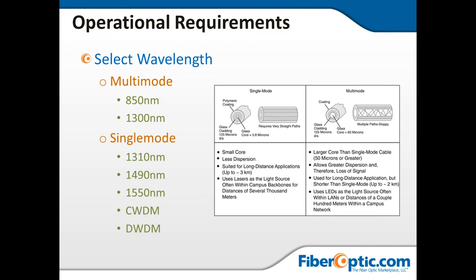You can run a SONET on one wavelength and a pure gig-E Ethernet kind of protocol on another wavelength. And something as simple as just an ATM transfer protocol on another wavelength altogether, and that will allow you to expand your system using the existing glass.